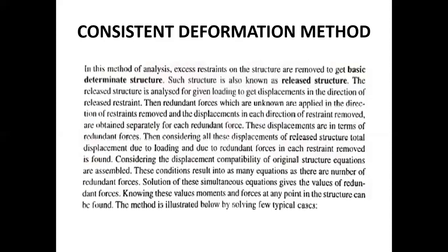Then after releasing the extra forces, when we get a determinate structure, the strategy would be analyzing the determinate structure using the basic equilibrium equations. In this case, displacement compatibility equations of the original structure are assembled, and then these are solved. That will help in the analysis using this method.